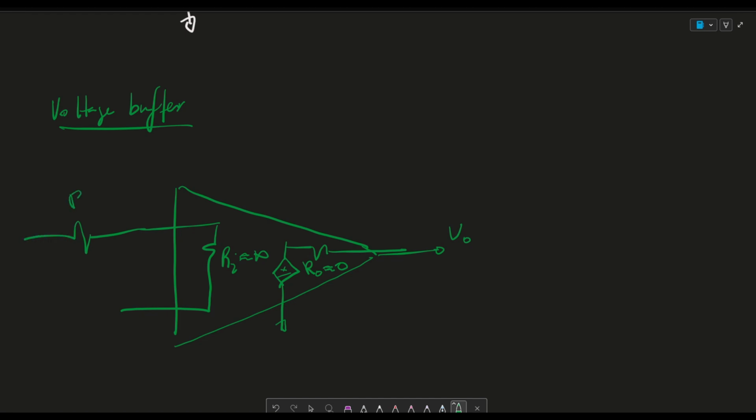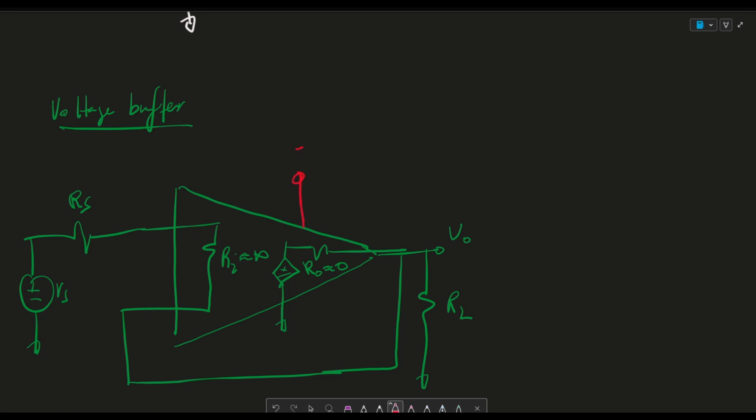And this is the source resistance. And this is the source's voltage. And we loop this system back over to the V out. And we can also connect an R load here. And this R load could be a motor, it could be a speaker, or anything like that. And don't forget, your op-amp always has power rails. So plus 10 volts, minus VCC, minus 10 volts. Again, this is where it gets the amplification from, right?